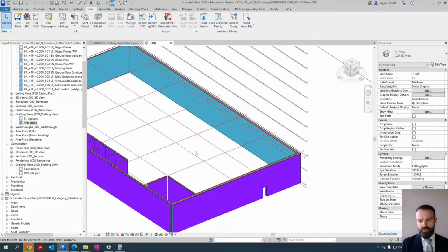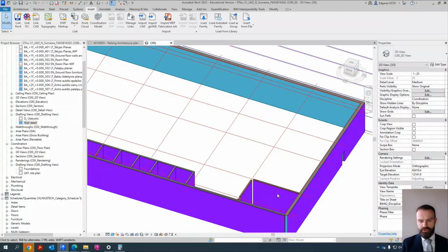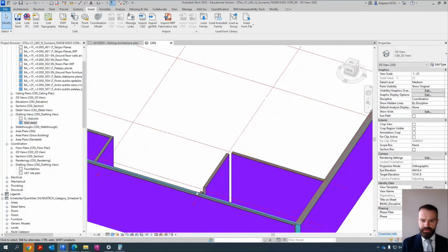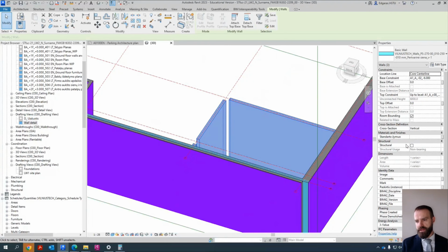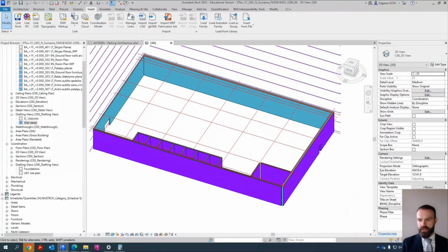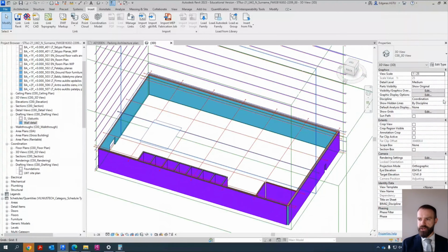And let's say for my car parking project, I need to create additional walls, additional openings in the walls. Also, I need to change the status of these walls, because these walls are bearing walls. So I should activate structure and structure bearing elements for these staircase walls. And you can see if your walls are structure or not structure by changing discipline.